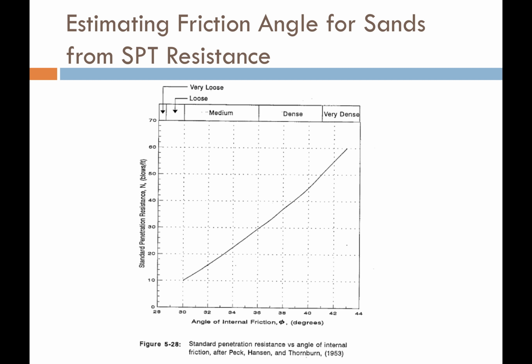This is a useful chart. If you don't know the friction angle, but all you have is standard penetration testing, you can correlate the standard penetration testing to drained friction angle if you're dealing with sands or sand-like soils.